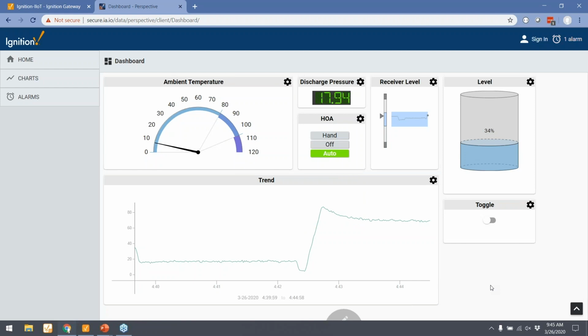And so now, Benson, if you can, I don't know if you're already showing the camera or not on that, but we can actually show the control and how from here I can write to that and have that being sent to the broker, I think ultimately over that cellular connection, go all the way down to the Epic, out to that PLC where we can turn that thing on and off. Yes, indeed. You're going to be talking now to the Epic, which is using Ignition Edge and the built-in drivers to talk to that PLC that's over on the left-hand side of the screen. And indeed, when you press that toggle switch, that's going to turn on a stack light that's right above that enclosure where the PLC exists. How about that? So very nice and easy.